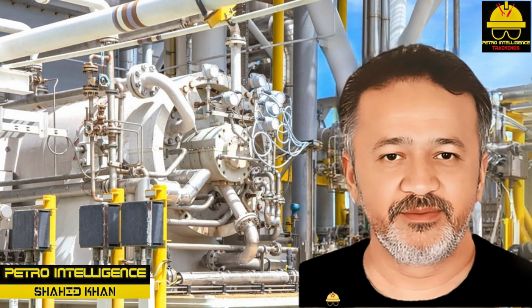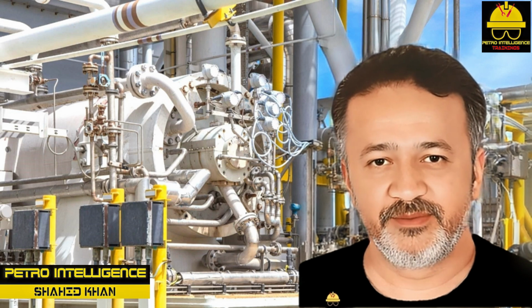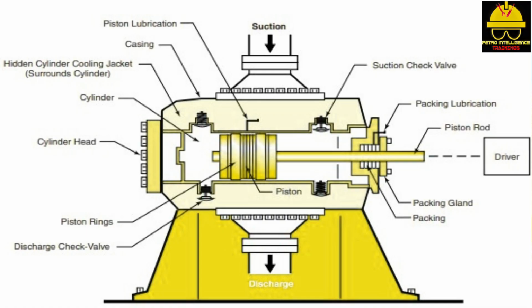Reciprocating piston compressors. Their distinctive back-and-forth motion characterizes reciprocating compressors. Reciprocating compressors are classified as either piston or diaphragm. Diaphragm compressors utilize a hydraulically pulsed diaphragm that moves or flexes to positively displace gases. We discuss only the piston type because it is the most popular design. Equipment ratings from fractional horsepower to over 20,000 horsepower are possible on reciprocating compressors. Pressure differences of below atmospheric on the suction side to over 30,000 psia on the discharge side are possible.